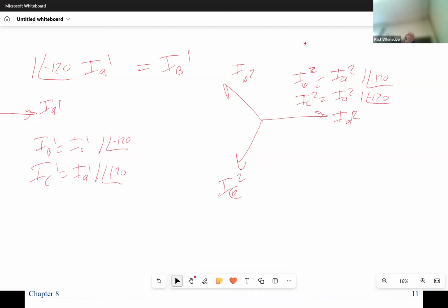So now my 9 that went to 7 went to 5 and now is at 3. So all I need to calculate is IA0, IA1, and IA2, and I can calculate all the other symmetrical components just by phase shifting. Because IA0 and IB0 and IC0 are all the same, so there isn't any work there.